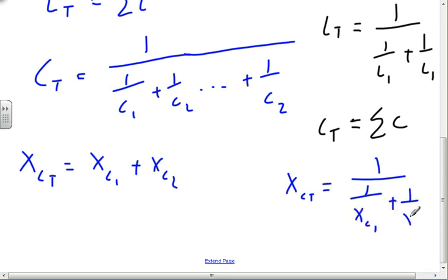So once I've calculated the capacitive reactance X of C's, I would then do the math just like I would do resistance, keeping in mind that it is at a minus 90 degree angle. As long as all I have is capacitive reactance, I can drop the angle and add it at the end, because if I bring it with me through the whole calculation, I'm still going to be at minus 90 degrees when I get done.